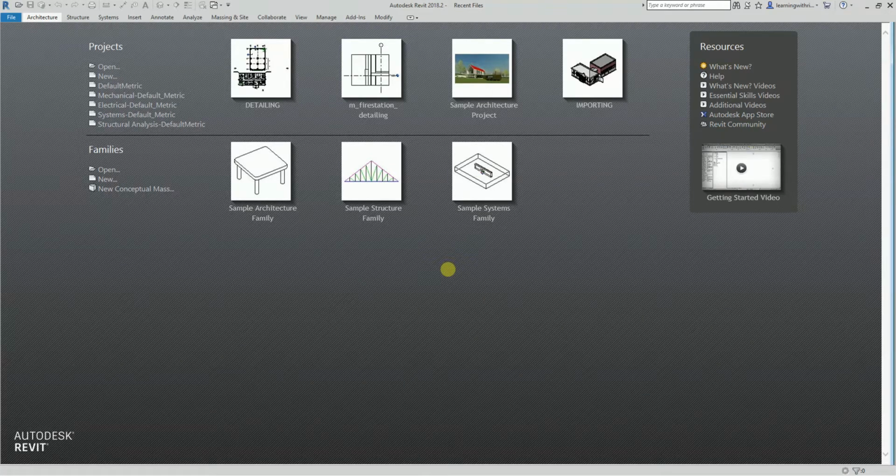Now this time around, I'm going to teach you another way that you can create detail in your project. And this time, we are going to discuss drafting views. Drafting views always appear in the examination as well. Okay? So usually the reason why we use drafting view is to create view-specific details that are not part of the model design.